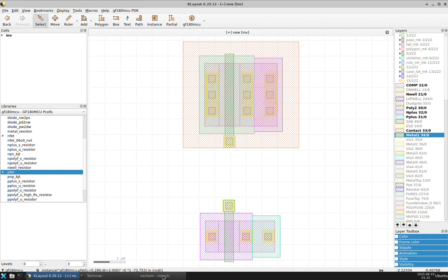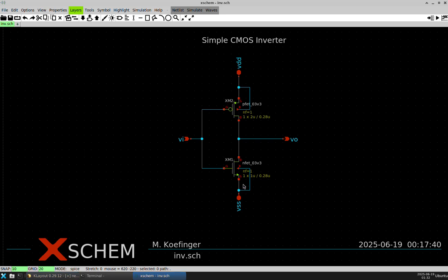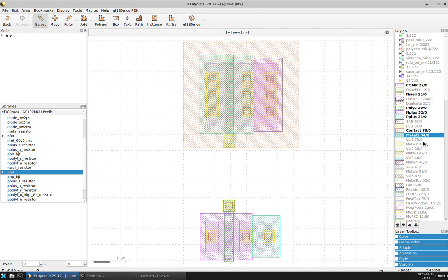now let's go forward and do the interconnections. We only had 2 transistors, so we're done with placing more components. We only need to do the interconnections. So we're gonna connect the gates together, sources and bulks together, and then the drains together as the output. So I'm gonna start with connecting the bulks and sources for both transistors. For this, I'm gonna use metal layer 1 and then select box right here.